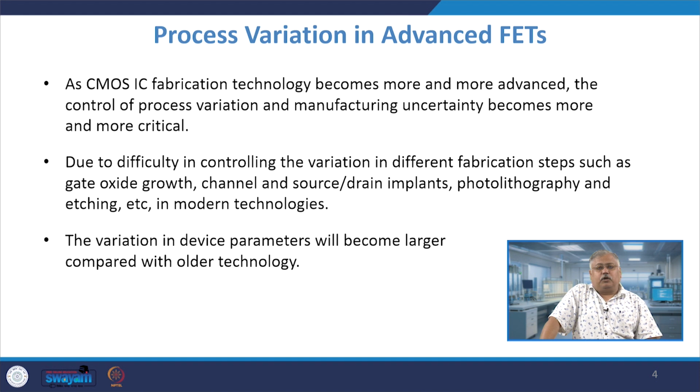Okay. So, let us look at the process variation in advanced FET. What do you mean by process variation? See, when you are at the design stage, you use TCAD tools to design the devices, and then you use your EDA tools to extract the circuit aspects of those devices. However, when you actually go to fabrication, then whatever you have given in the design flow may not be exactly replicated in the process flow, right, and there will be therefore some process variations available to us.